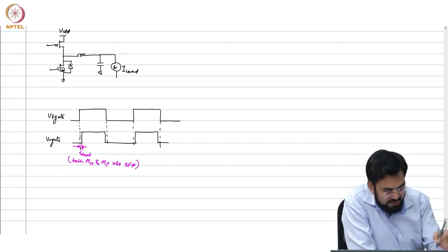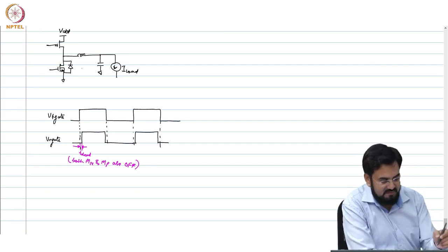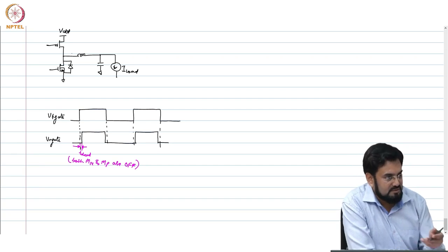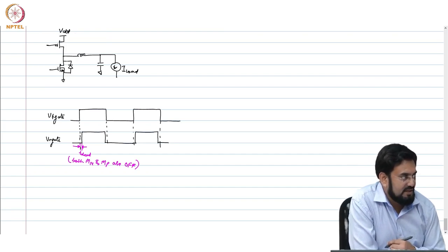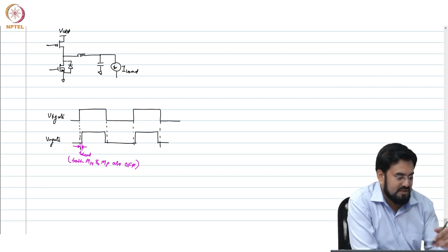So this will only go to negative. So the PMOS will have a P here. So that will always be reverse bias. That will not conduct, because current direction is going from this towards load. So this will always be negative during that time. Okay. So that diode will not conduct.